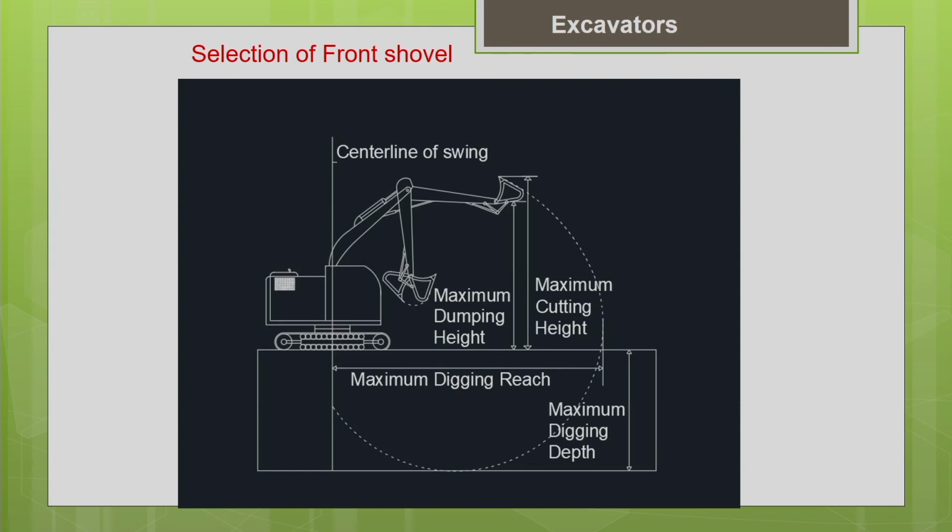So for your project, what is the maximum digging reach needed? What is the working radius needed? What is the maximum dumping height needed, depending upon the truck available? What is the maximum cutting height needed? You know it for your project. Accordingly, you can make the selection of the shovel: match your job requirements with the machine specifications and make the selection.